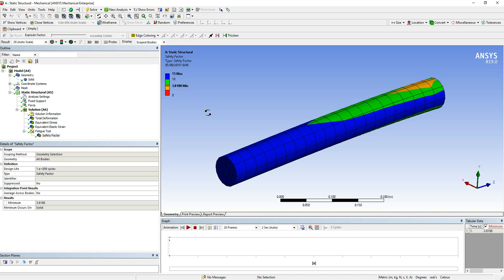Then you introduce a factor of safety of 2, so you divide that and you get 500. You design it to 1,000, but you sell it with the capability of 500, and it has a factor of safety of 2. It could be doubled for its true performance. This gives you an operational window of how well it will perform in certain states. Now in this loading state, this is what you get.